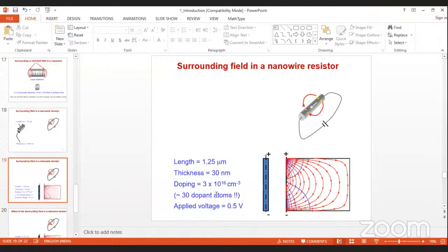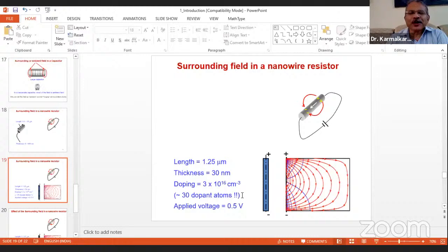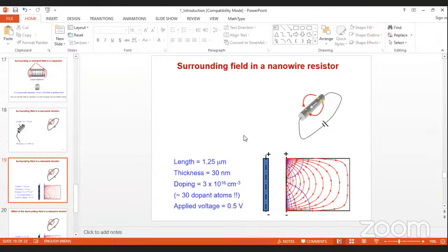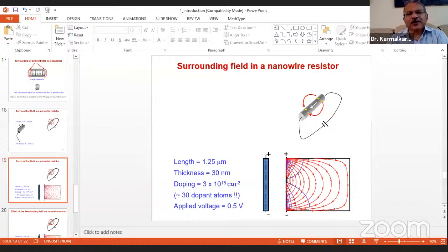Is it volume, sir? Correct. So you tell me, what is your formula? That's the doping level divided by the material volume. See, this doping is per centimeter cube. If you divide by centimeter cube, you will get per centimeter power 6. So it can't be doping by volume. What should it be? Can you please correct yourself? Doping into volume, because doping is per unit volume.